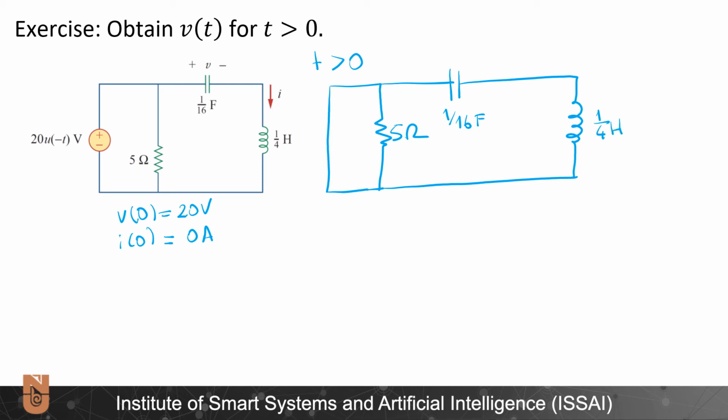But since I have here the short circuited part, this 5 ohm resistor will not pass any current because all the currents will be going through the short circuit and it will be effectively bypassed. So therefore I can remove this, and I end up with my final equivalent circuit.